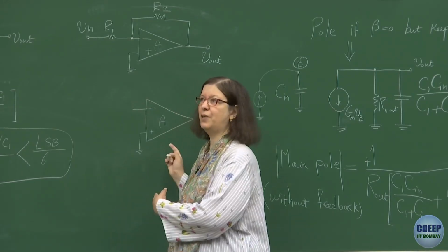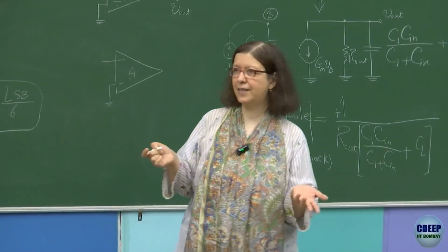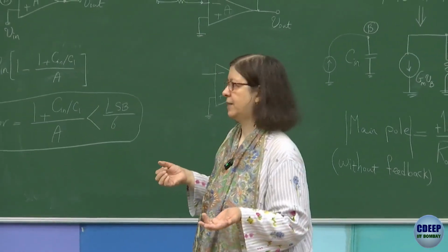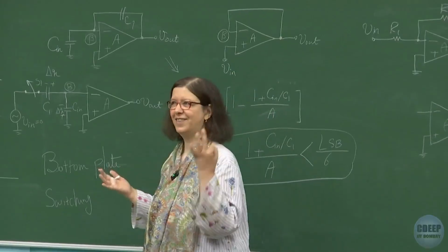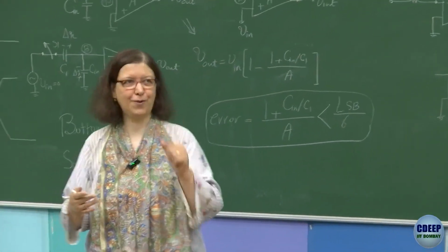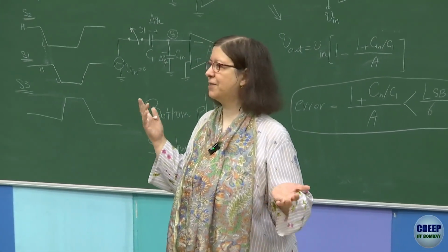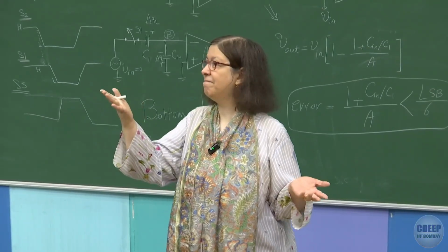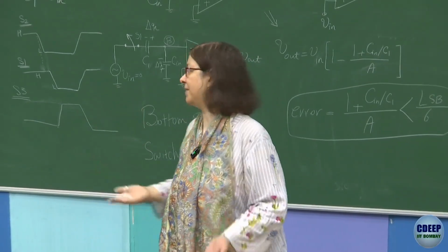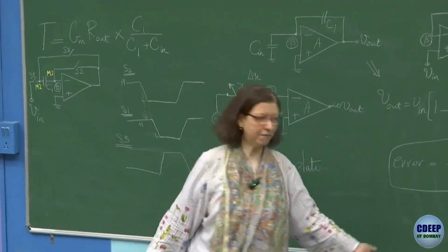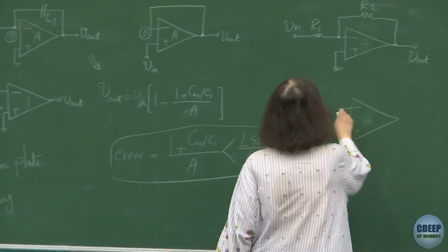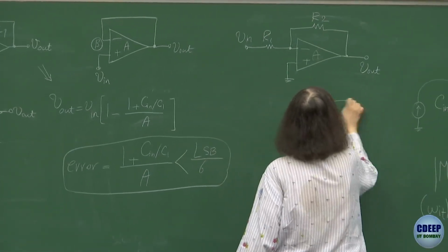What can we replace if I want to get a gain? See, in discrete time, we have switches, capacitors, op-amps as of now, and comparators. So what can we use? Yeah, exactly. We already had a switch cap here, right? Why not use it here? In fact, in a steady state, I can have this kind of circuit.